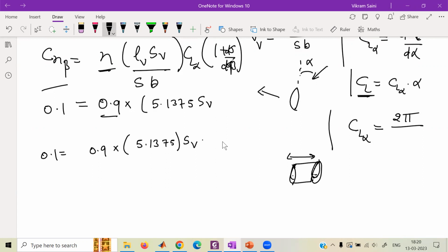Now, because of the finite length, the CL alpha will not have that theoretical value. Not just because of it being finite, there are other effects that are also at play. So, how do we modify CL alpha? By what factor should it be reduced such that it is more realistic for a wing? Om, do you have any suggestions? Let's say you know the theoretical value of CL alpha for an airfoil. The question is, you have a finite wing. So how do you modify that CL alpha to be used?